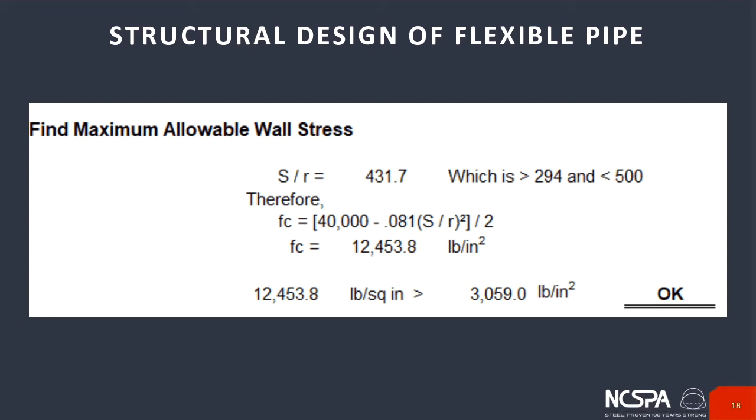So essentially you would take the yield strength of the material, divide it by a factor of safety, and that would be the limiting stress allowed. As structures become more slender, so this KL over R ratio, or in this case for pipes the span over radius of gyration ratio, gets larger and larger, you go into a buckling mode, which will control what the allowable stress would be.